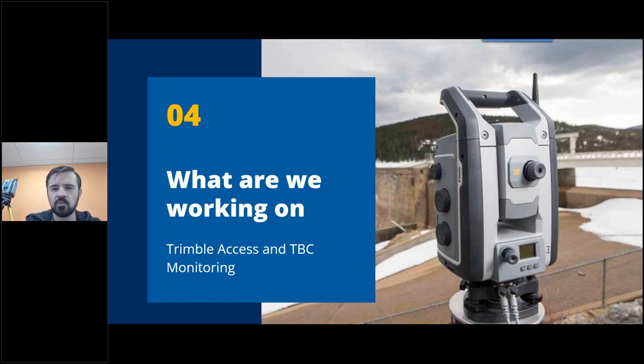Looks like there was a question asked: do you have monitoring with the Trimble SX10? So you can use the Trimble SX10 with Trimble Access Monitoring. You can use it for automating the total station rounds. You can also perform scans, and you can take multiple scans that you've made with the SX10, bring them into TBC, and do, for instance, scan-to-scan or surface-to-surface comparisons and see the heat map of the deviations on the structure. So yes, that is possible. It doesn't look like there's any other questions, so we'll keep moving on. Thank you for that question.